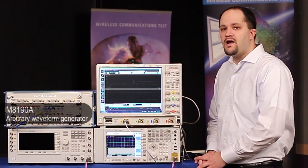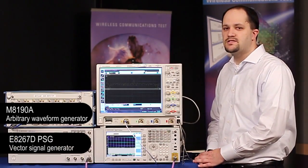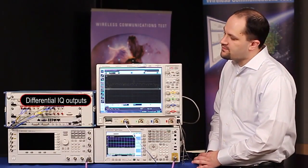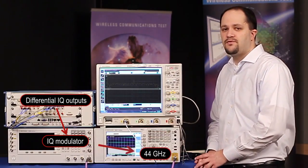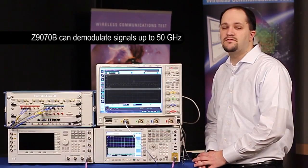Also, we have a wideband arbitrary waveform generator and a vector PSG to generate these wideband signals. The M8190's differential IQ outputs are connected to the vector PSG's IQ modulator, which then upconverts a signal up to 44 gigahertz. Our analysis solution can demodulate or analyze signals up to 50 gigahertz.